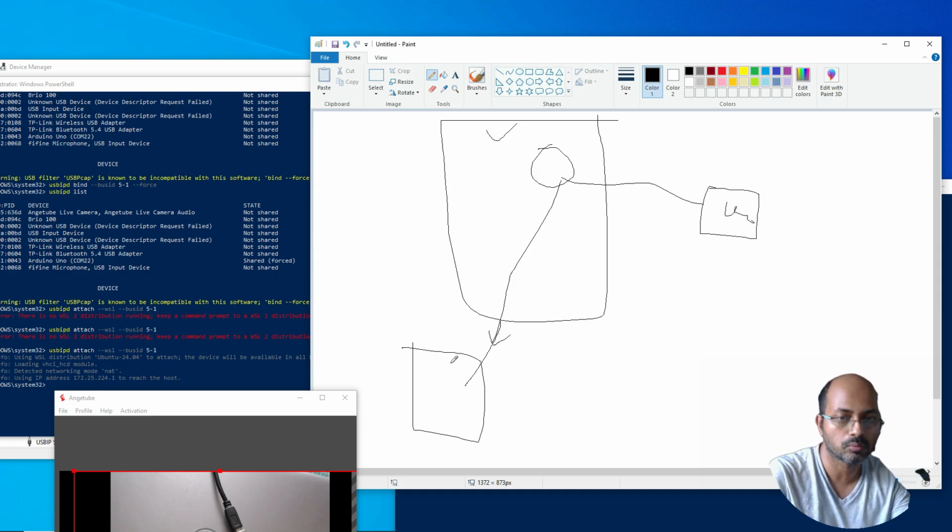We have to open one more Ubuntu terminal where we subscribe to this and create a UI console, not a GUI, where we want to see physically where the robot is on the floor. And then we will create one more PowerShell, and here we will give commands for the robot to move left, move right, and we will see the robot physically moving.